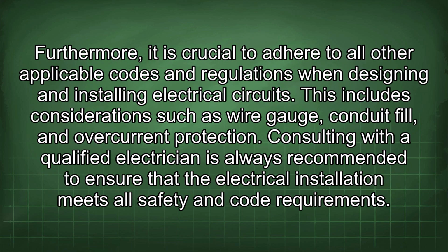Furthermore, it is crucial to adhere to all other applicable codes and regulations when designing and installing electrical circuits. This includes considerations such as wire gauge, conduit fill, and overcurrent protection. Consulting with a qualified electrician is always recommended to ensure that the electrical installation meets all safety and code requirements.